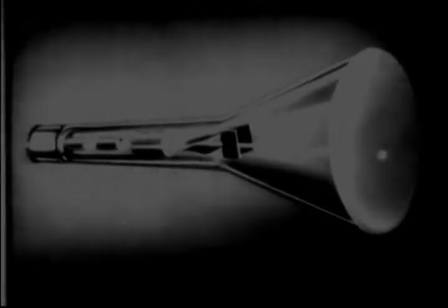The pips are formed by the action of the vertical deflecting plates, which bend the beam up and down each time a signal pulse is received. Thus, you can see that the electron beam is affected by both the horizontal and vertical deflecting plates. This is the usual type of A-scope. But these two sets of plates, by working together, can form any number of different scope pictures. For example, by changing the polarity of the voltage on the vertical plates, you end up with an A-scope on which the pips appear as negative deflections, like this SCR 582.